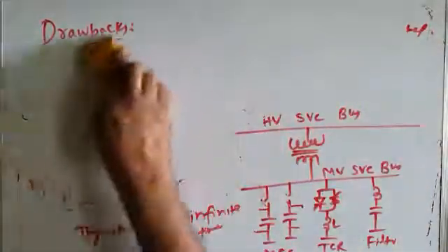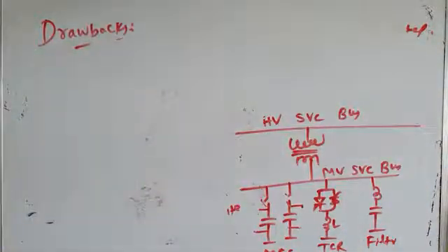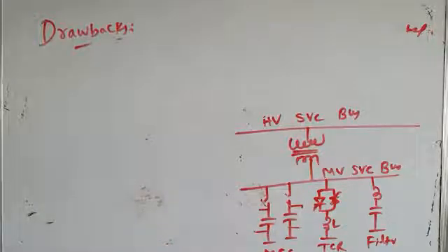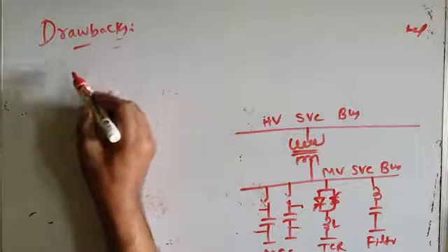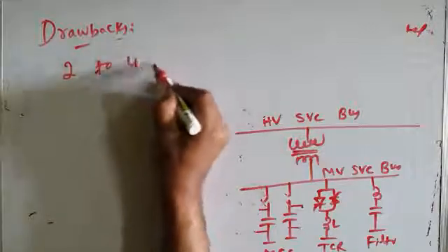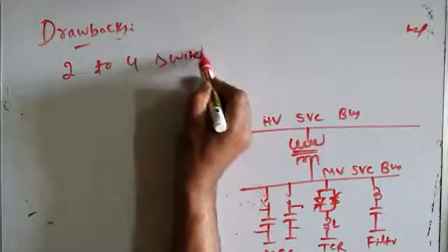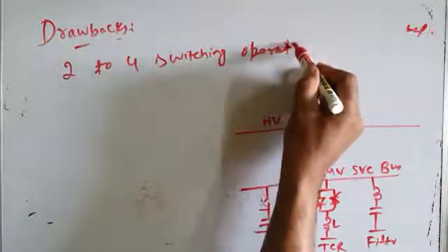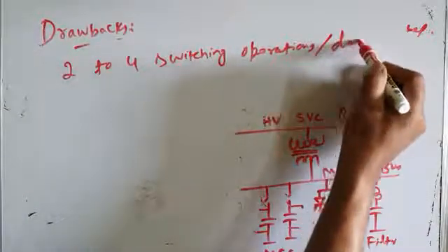So generally that's why I said in the beginning itself that this MSC, TCR, SVC is suitable only in those applications where only a few operations are involved in a day. For example, they are used in those applications where 2 to 4 switching operations only are required per day.